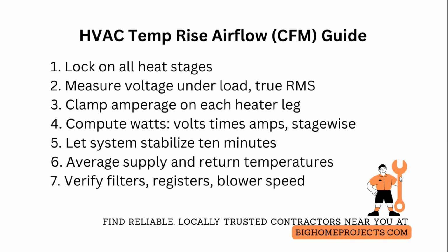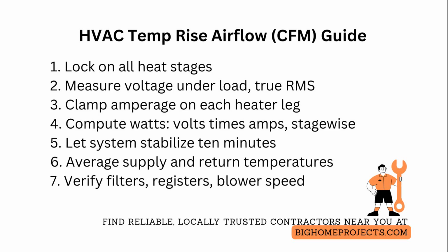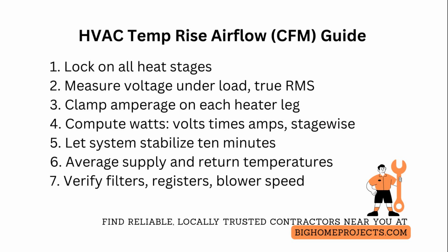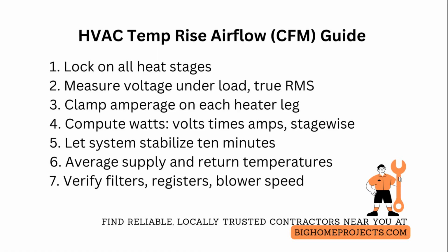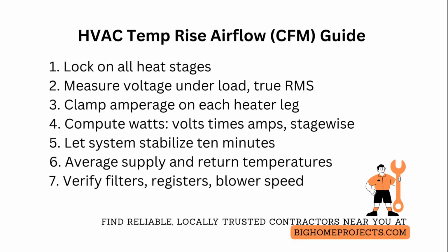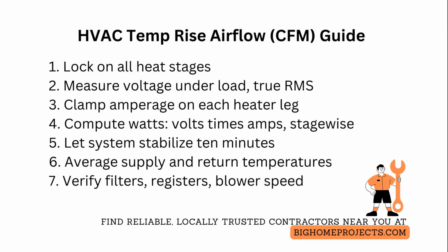If not, assume standard density, but note that high altitude will reduce density and change the cubic feet per minute results slightly. Confirm that filters are clean, registers are open, and the blower speed tap matches the heating speed you intend to test, because restrictions will raise temperature rise and make cubic feet per minute look falsely low.